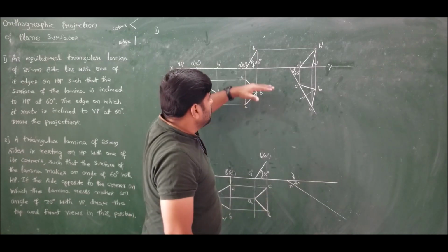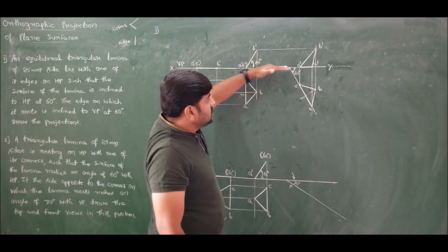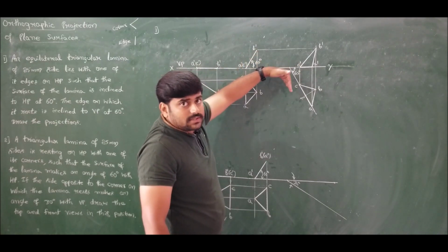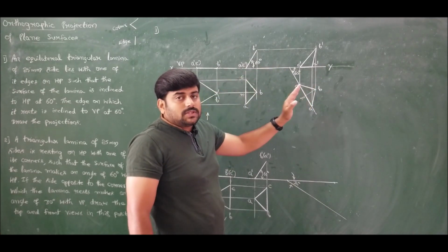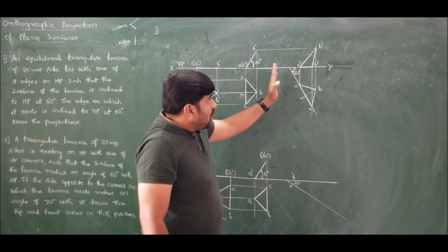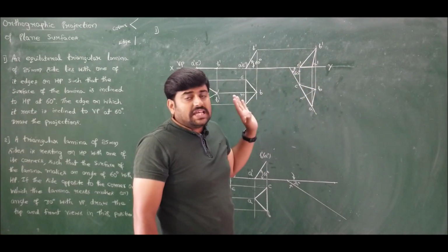We will always rotate second position front view counterclockwise, whereas third position top view clockwise. We will maintain the common method to solve problems so that we can avoid confusion. However you solve, any of the 4 solutions you give is correct for each problem.